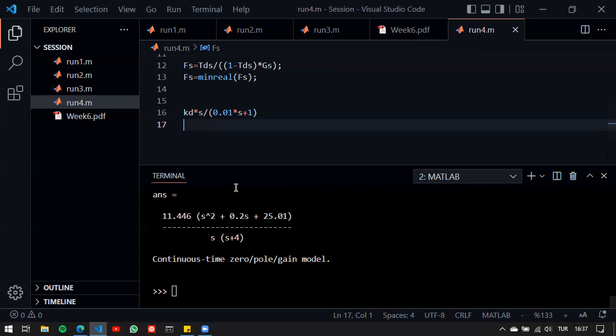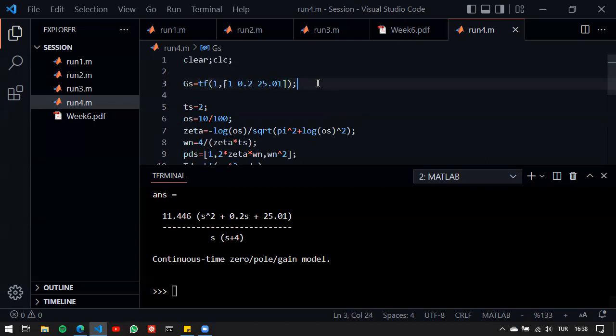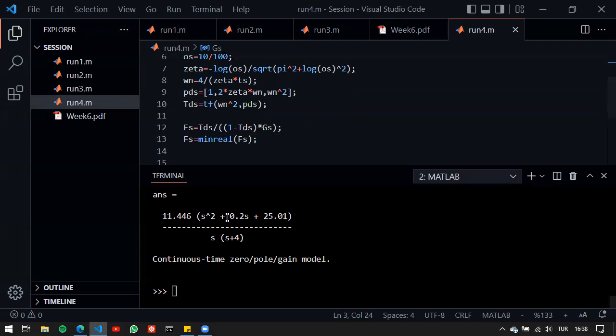Now, the question was, isn't it a good thing that we have a realizable controller here? For this system especially, this is the case, but for most systems, the model matching controller does not give us a realizable controller. It gives us a high order controller. Think of a fourth order system: if we had a fourth order open loop, there would be 4 zeros in the numerator and some poles in the denominator, which would make it hard to realize.